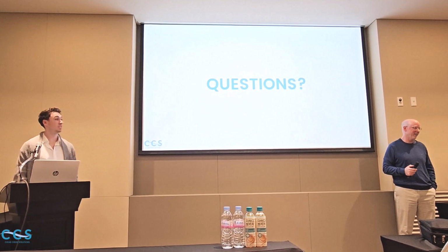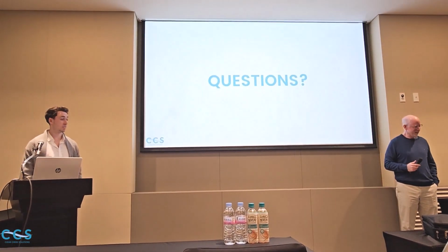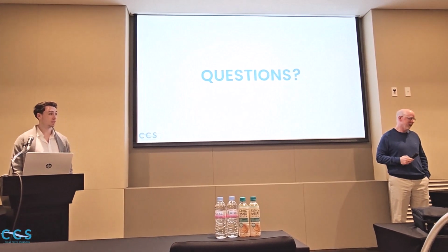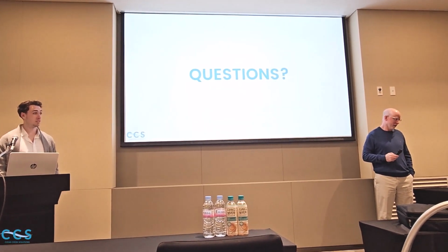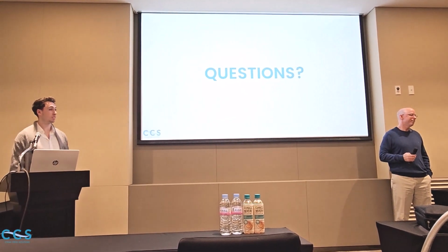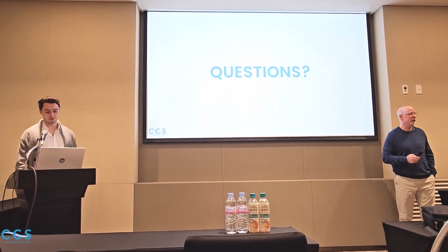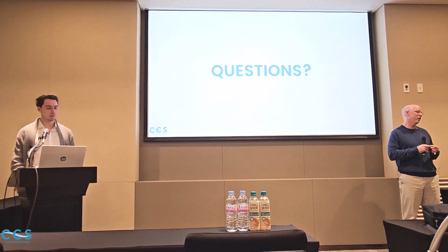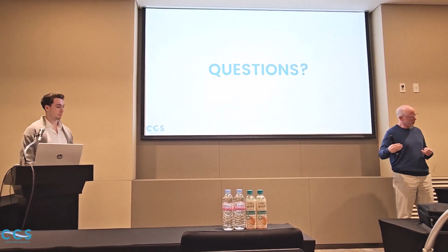Yes, some Korean researchers have applied HSPF for simulation of water quality models. Good, yeah. But I don't understand how to calibrate. Yeah, calibration's very difficult. It depends on how many monitoring sites you have, when they were monitored, and how reliable they are.